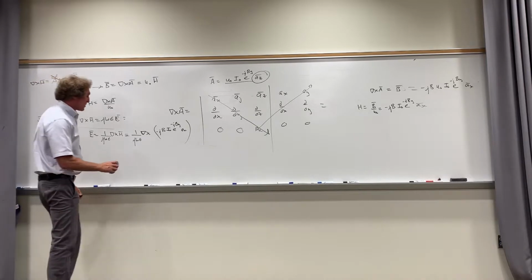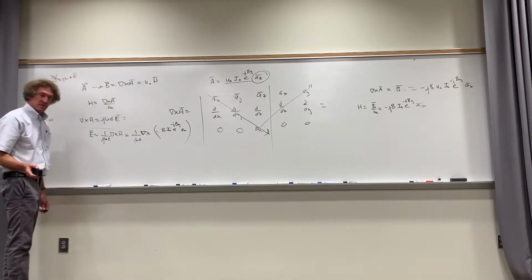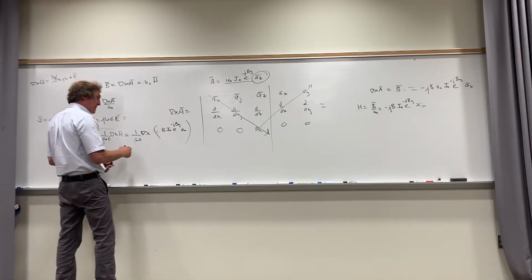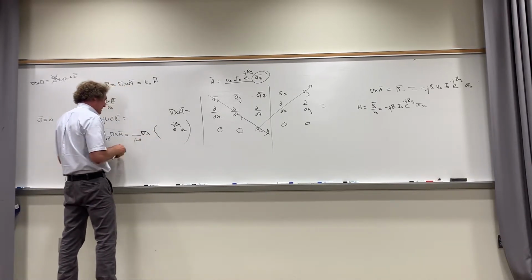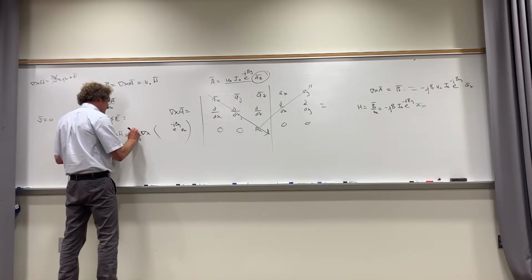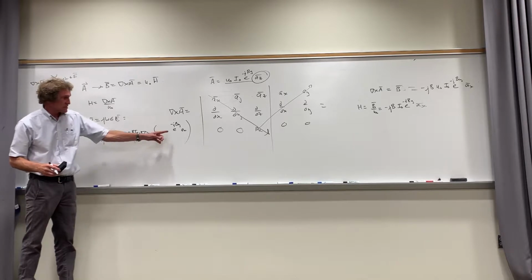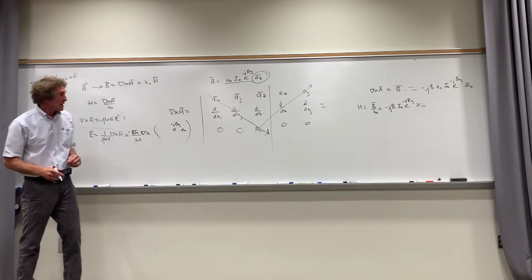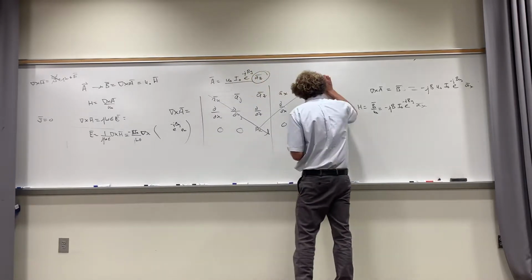Now, at this point, I'm going to erase the J's because they appear in both places. And I'm also going to take the beta I naught out in front, and the minus sign. So now I take this, and I have minus beta I naught out here. Now the only curl I really have to deal with is this term. It's got an X component, and it's e to the minus J beta y, correct, class? So that's an AX component. Now I'm going to go back up here and do it.